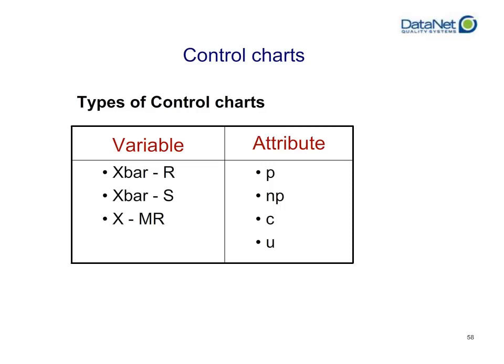Attribute charts are of a completely different nature. There are no spec limits. Charts include things like the P chart, NP chart, C chart, and U chart. The most common one for defective units is a percent chart or P chart that shows you the percentage good, and you can actually flip that and call it a Q chart. Then you can look at the percentage bad instead of the percentage good.